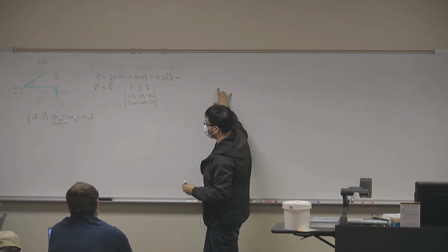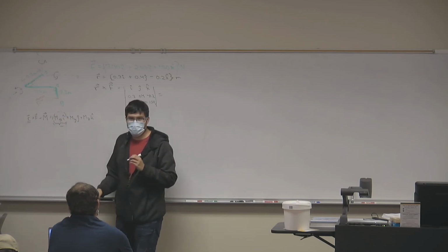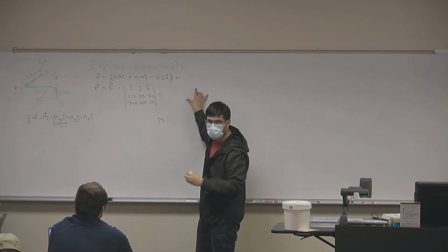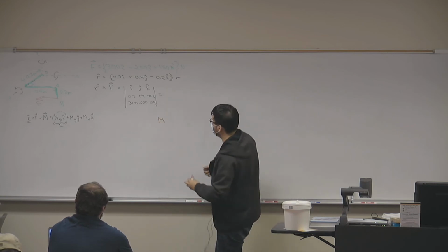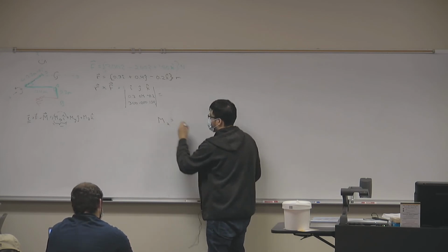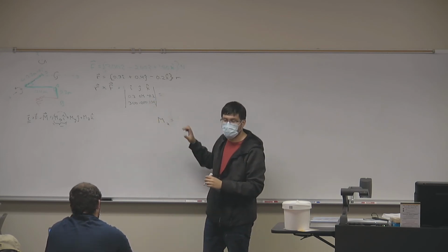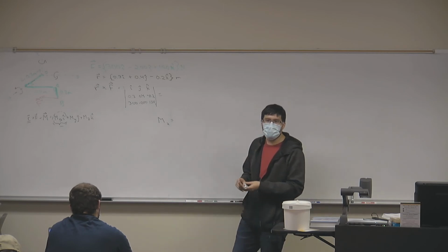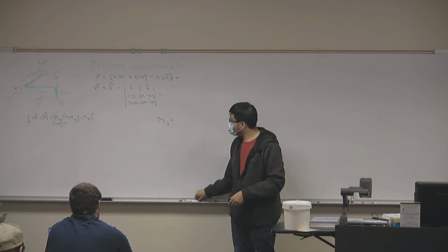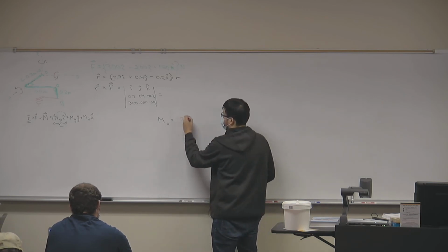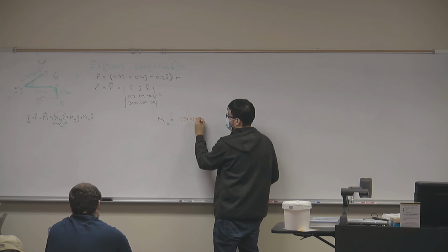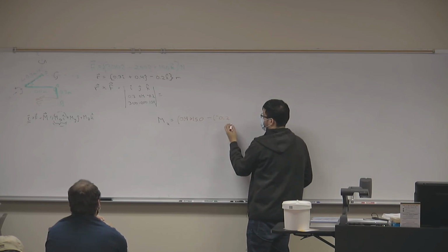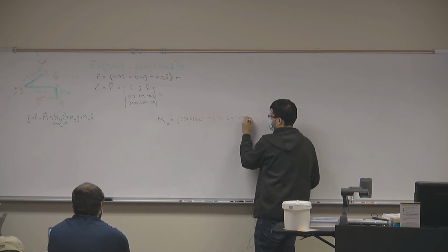So we can get a whole moment for everything, but we only care about the x component, right? And what is the x component of this moment? You can solve it yourselves here, but I want to finish on time. Looking at this determinant, looking at this matrix, what's my x component? You don't have to give me the final number. Just tell me what I need to write down so I can calculate it. 0.4 times 150 minus negative 0.2 times negative 200. Good.